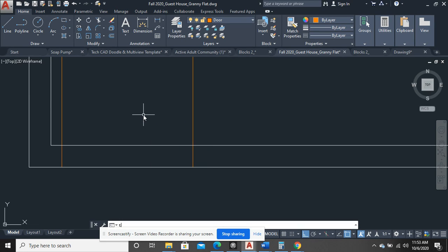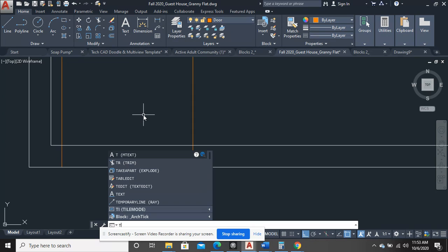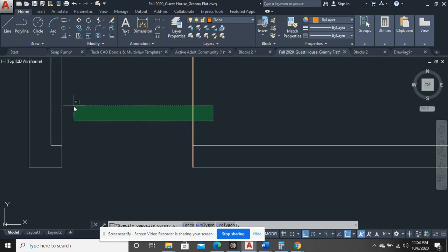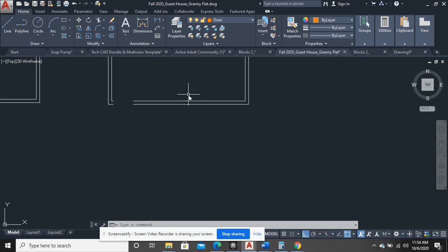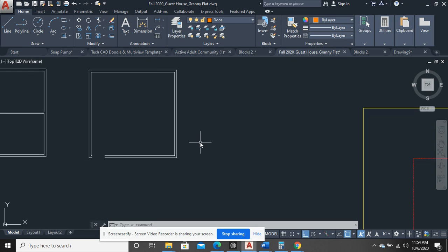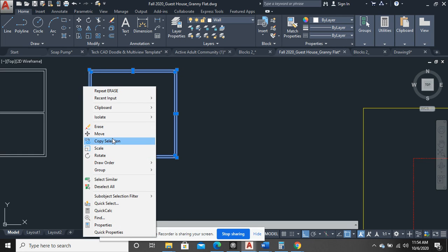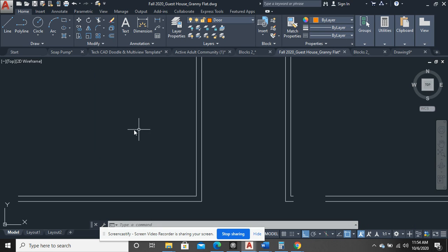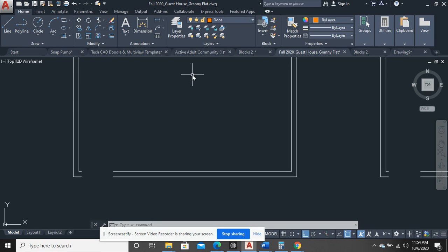And all I have left to do now is use my trim tool, TR spacebar. You should just remember that one. Right click instantly, click in there. And now I can go ahead and select this and just delete the opening. I'm going to make a copy of this for a second because the challenge I want to present in here, the question I want to pose, ties in directly to this.